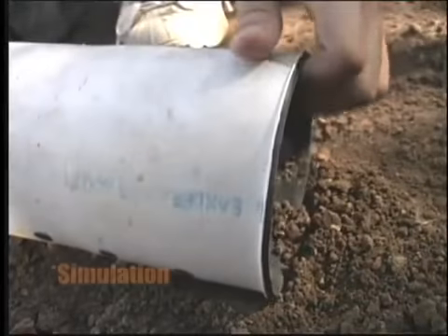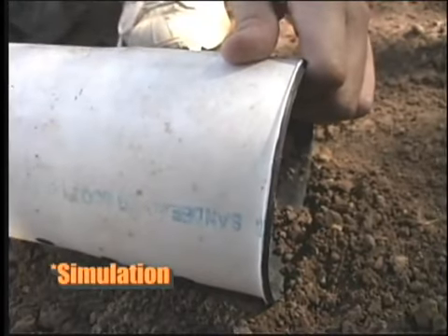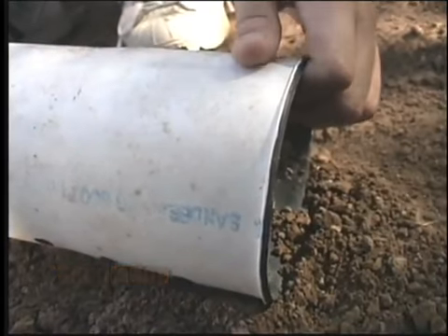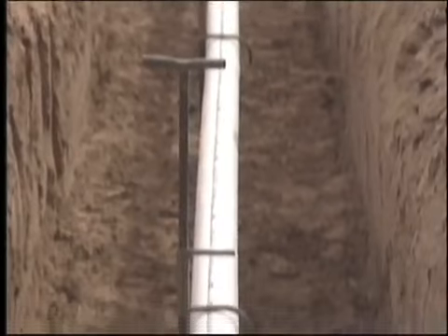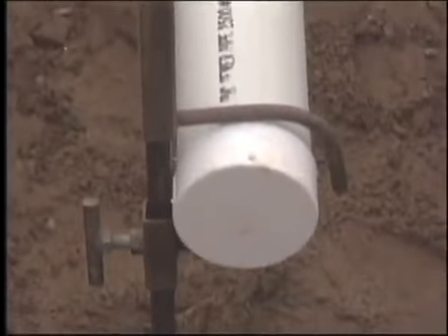During the assembly of the plastic piping in the trenches, it is important to ensure that the perforations are not at the bottom of the pipe. Ensure outlet holes are at 4 and 8 o'clock positions and do not point straight down. Place caps at the end of the pipes if they are not connected.